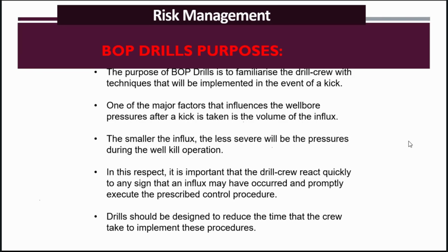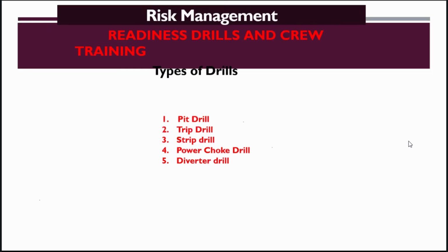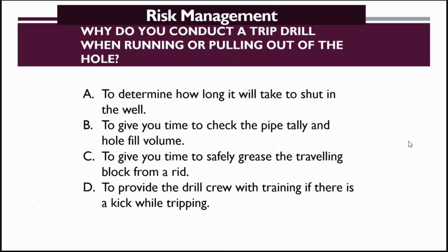There are many types of drills. Some drills are on a monthly basis, some quarterly, based upon company policy. But a drill means practice. This practice session occurs as part of well control training, so that all the crew are familiar with what procedure to take if such a situation occurs, and what our role and responsibility is. So this is part of training. There can be a pit drill, trip drill, strip drill, power choke drill, diverter drill. Many types of drills are there.